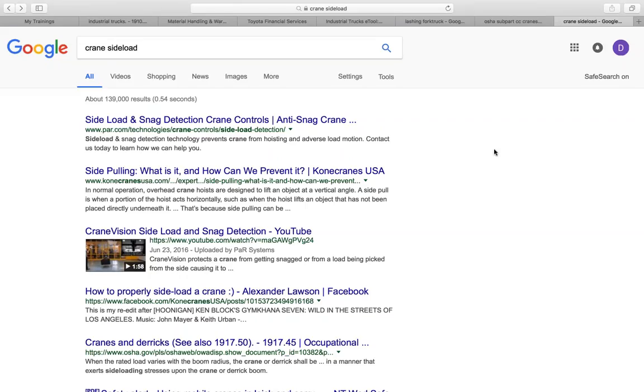And then in addition to that, what are we talking about? Equipment load ratings only extend to the hook, block, the slings, the equalizer beams. So load ratings are for everything, right? They're for any attachment, any component of the crane itself, or any rigging equipment as well.